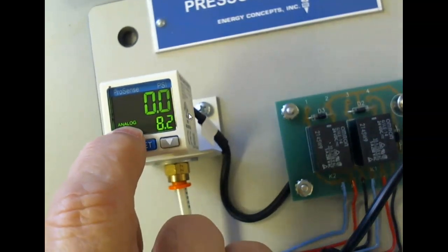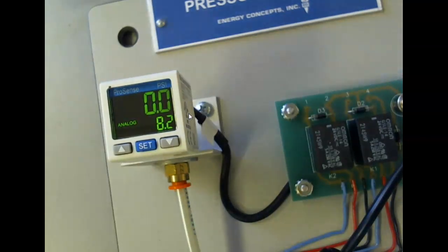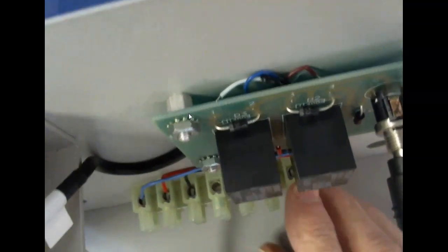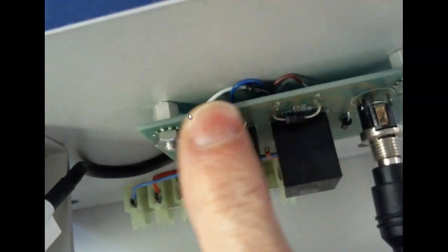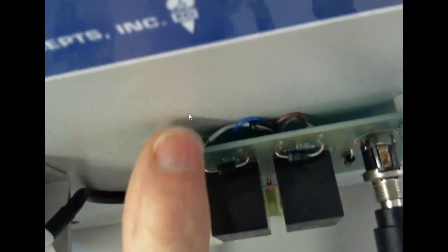So the 5th wire would actually be the analog output, right? This will give us an output voltage that is proportional to the temperature, and we can look at it and see what that is for our transfer function. Then it's got 2 other wires, a white and a black, so it's got 2 contacts if we use it as a digital sensor.